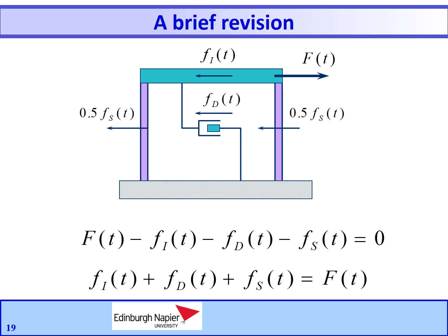It can be given satisfactorily by a linear viscous damper or dashpot, as you can see in this more advanced equivalent frame. The damping coefficient is selected so that the vibrational energy dissipated is equivalent to the energy dissipated in all the damping mechanisms combined present in the actual structure.